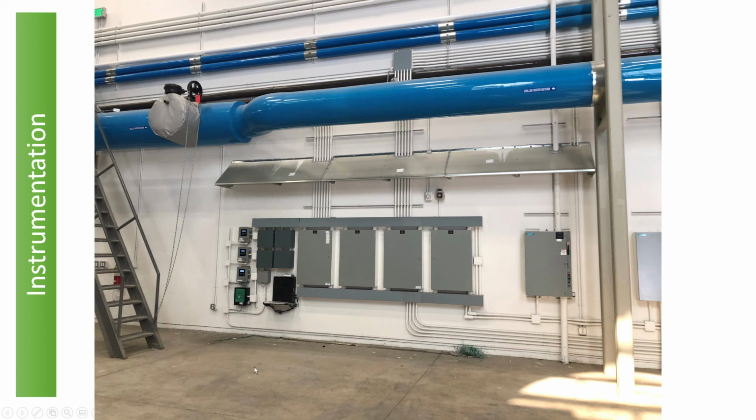And to give you a bigger picture of how all this control communication works, this little meter right here is the BTU meter we just saw. There's a BTU meter going to the east side piping, a BTU meter on the west side piping, and a BTU meter on the primary loop, which is just the loop of water within the plant that's being circulated through the chillers. And then all these other panels are receiving all of those signals that we have talked about and controlling all of the devices in the plant.